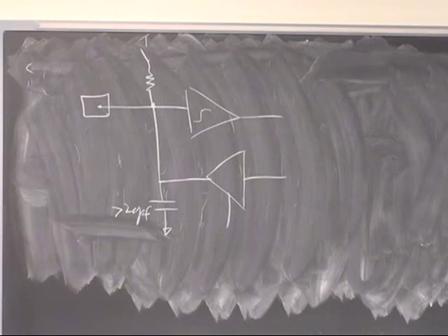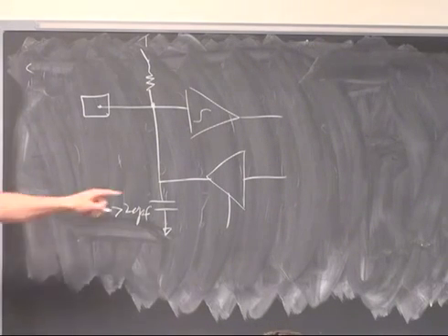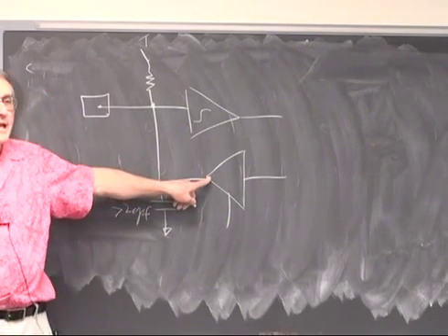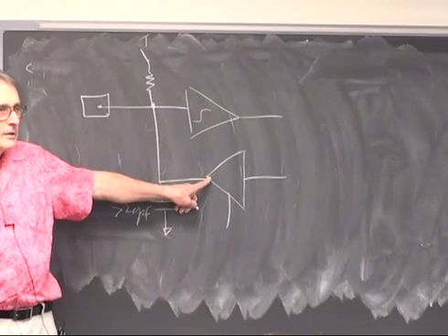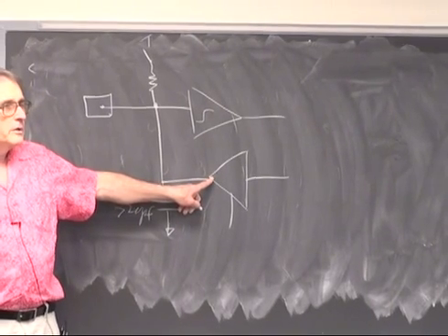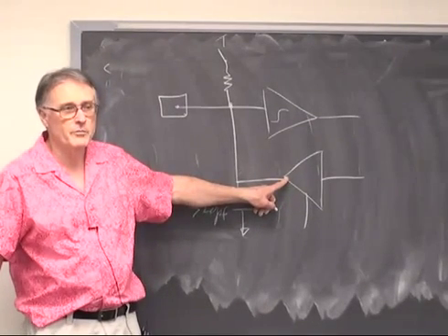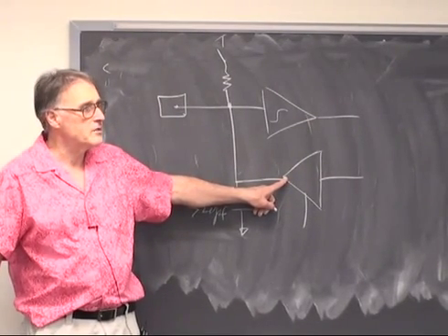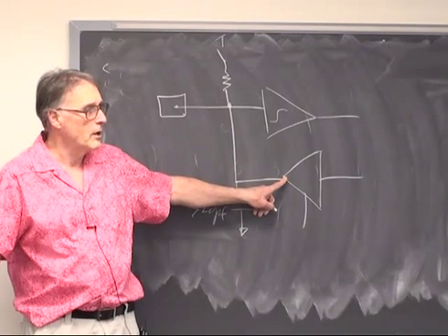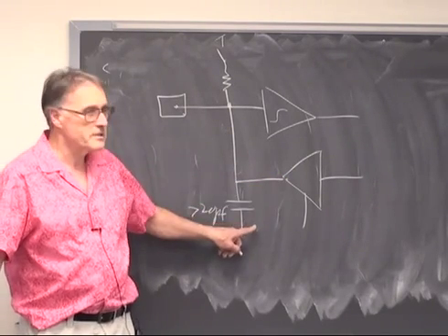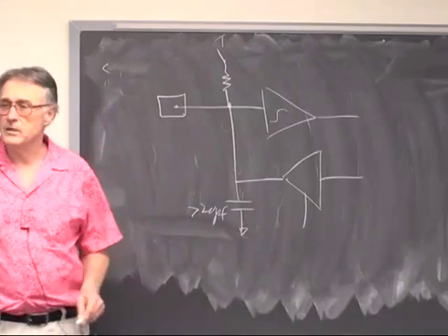You didn't put it on there, it's just there. So, if the tri-state were turned on, if you were driving this as an output, let's say that you turn on the output high, you let it come to equilibrium, and then you suddenly switch the output low. What's the time constant for switching from one state to the other?